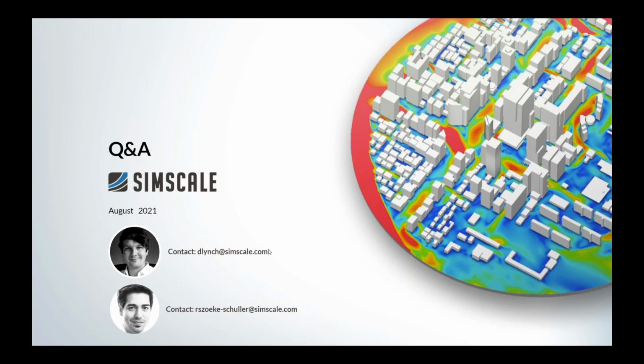Great. I think we have a last one coming in, which is, can I use a common EPW weather data file for seasonal analysis? I think that one is for you, Richard. Yeah, we do not directly support EPW, but there are ways to convert EPW to stat files. So, for example, with EnergyPlus, you can convert EPW to a stat file. But the stat file format itself is also very simple, right? It's more or less a table of velocities or velocity buckets versus wind directions, right?